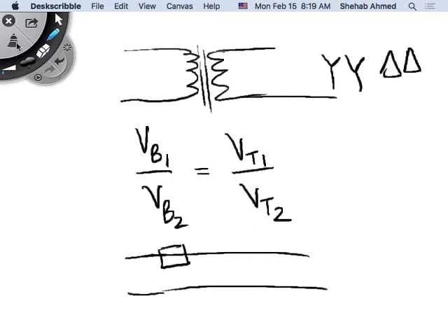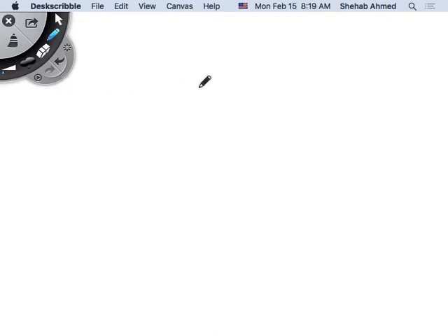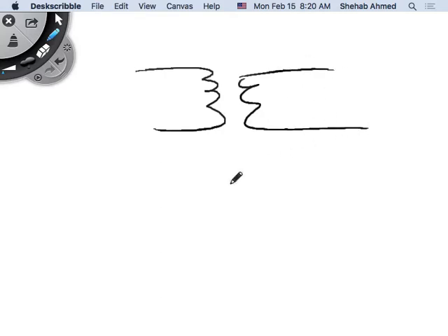Anytime you have a phase shift between the primary and secondary, you have to account for that. So what we will end up seeing is that we will end up with a transformer in the single phase equivalent circuit. Even in the per unit single phase equivalent circuit, we will end up with a transformer. But this transformer will only have a phase shift, and this phase shift will follow the standard. So we said that the high voltage will lead by 30 degrees.